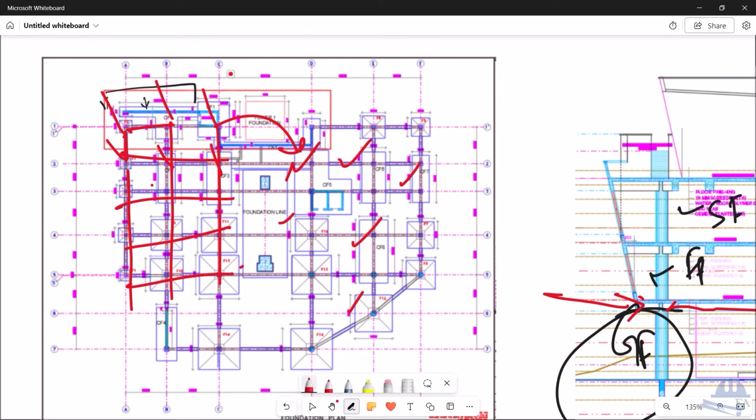So this all depends on your planning. You can do this way, and let's say that you don't have enough resources, you don't have enough people, then what do you have to do? Then you have to finish all the tie beams first, then you have to start the columns. Okay, and if you have the resources, and if you have people, and if money is not an issue and time is an issue, you have to finish the project on time. If time is an issue, money is not, then you have to mobilize additional people and do this way. So we'll do it like this, because mostly in big projects works are done parallelly. Okay, so let's go to Microsoft Project.